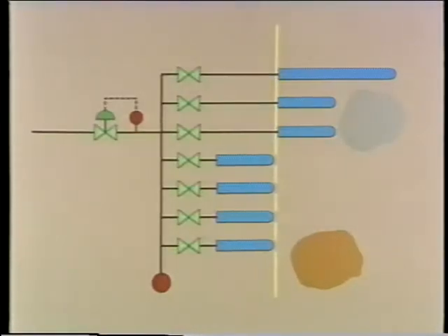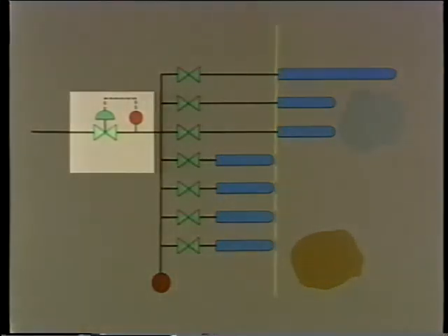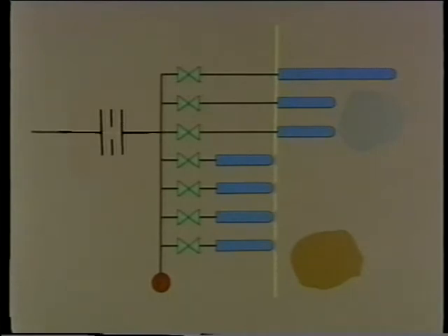Too high or too low a blowing pressure could be a problem somewhere else, at the source, or wherever else the pressure is regulated. Sometimes the valve that feeds the whole system may be adjusted wrong. Some systems use a restriction in the piping with an orifice of a certain size to restrict pressure. However, if the pressure is too high at the source of the blowing medium, this orifice will not control pressure as it should.